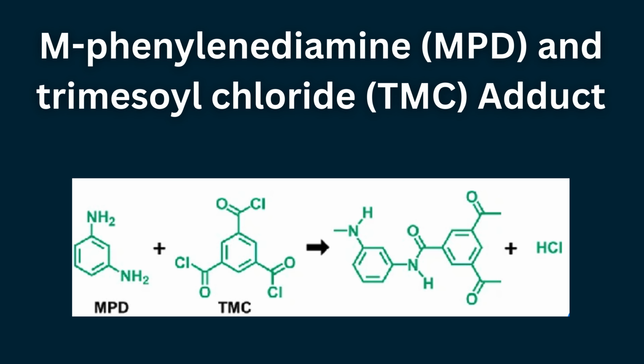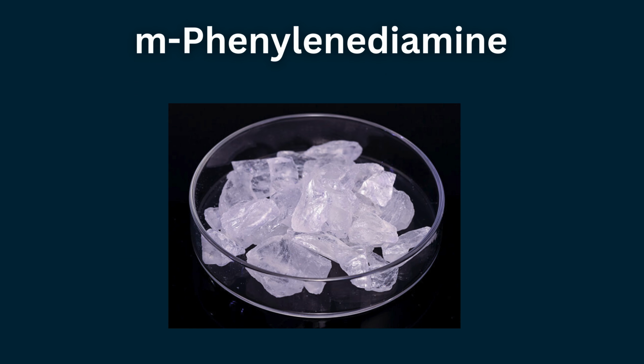3 general procedures are commonly used to mix MPDA with epoxy resins: Both the curing agent and epoxy resin are heated to about 65 degrees Celsius before blending. The epoxy resin is heated to roughly 80 degrees Celsius, and MPDA is gradually dissolved in the hot resin with continuous stirring. Technical grade MPDA may be heated to approximately 80 degrees Celsius and slowly cooled to produce a supercooled liquid that remains stable for several months at room temperature. During mixing operations, MPDA vapors and molten material can stain surrounding surfaces and irritate.